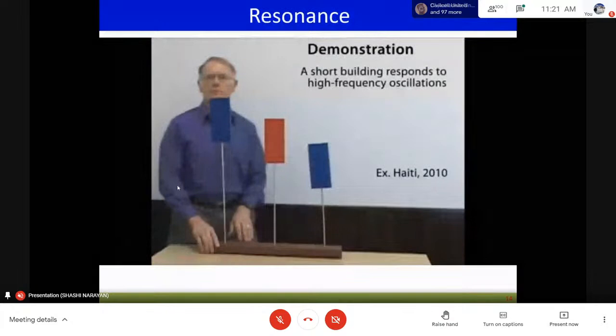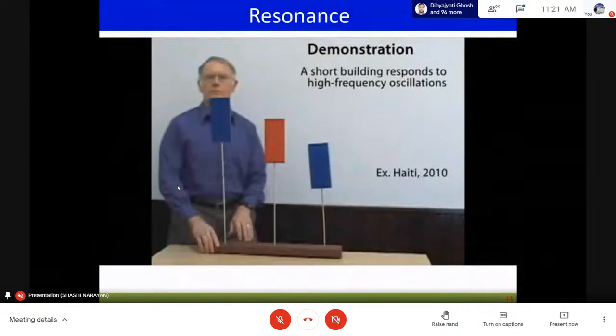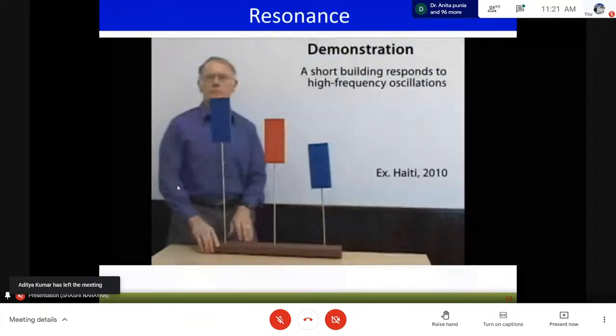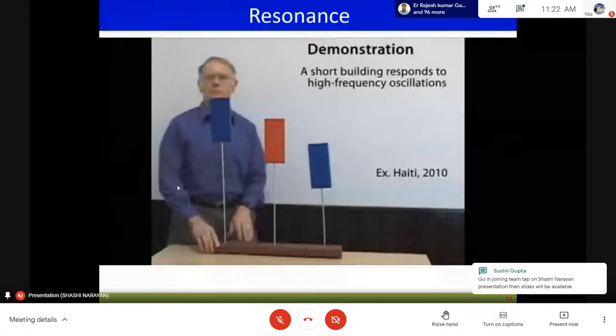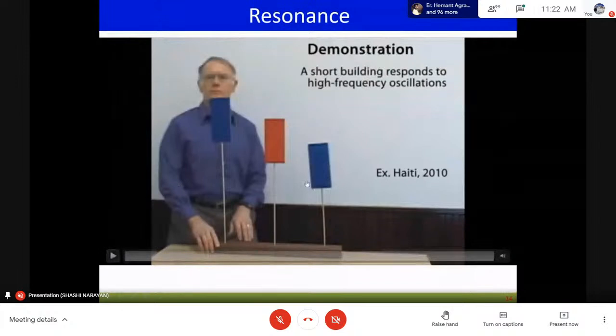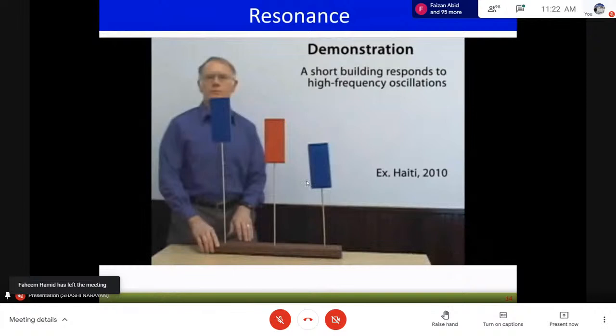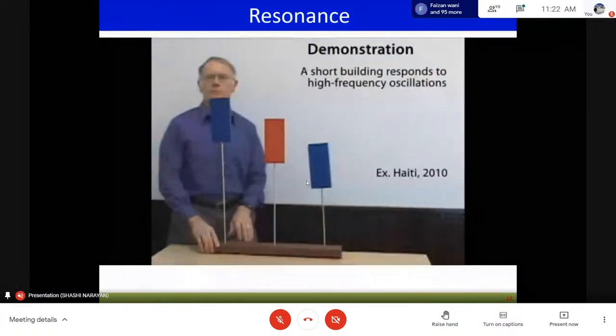Now there is a fourth effect to consider when dealing with an earthquake, that is the frequency content of the earthquake. That cannot be predetermined, and for this we need to go with nonlinear analysis. For the three quantities, that is the site condition, the zone factor, and the structure time period, we can go with linear or nonlinear analysis, and we can go with the static analysis. Whereas for the fourth quantity, the resonance effect which comes into the vibration, we need to go with nonlinear analysis, that is nonlinear time history analysis or experimental analysis.